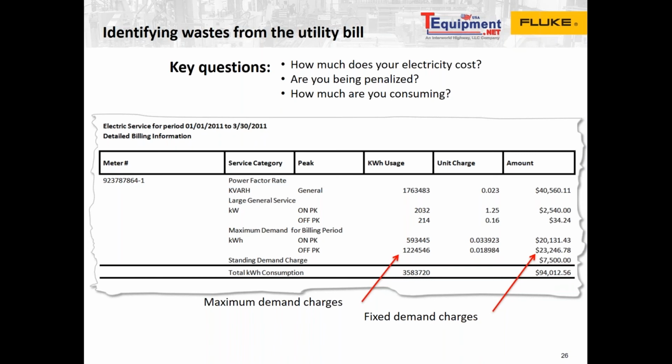And it'll show you where energy is being consumed when no useful work is being carried on during, for example, evenings or weekends. And it's important to compare these profiles against your known operating cycles and working time, because I've received questions before of, well, how long, I think I mentioned this, how long should I be measuring? How long until I know to stop measuring and then look at the data and figure out my energy usage? And I say, well, it really depends. It depends on your operational cycle. So you want to cover as much of your operational cycle as possible.